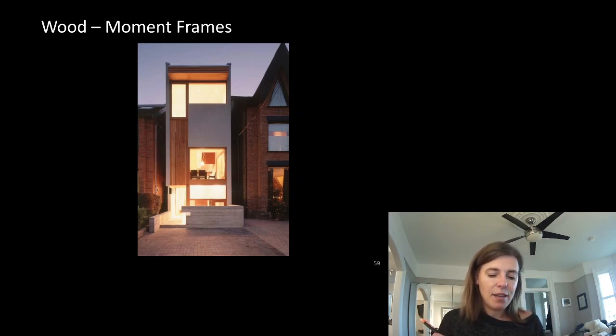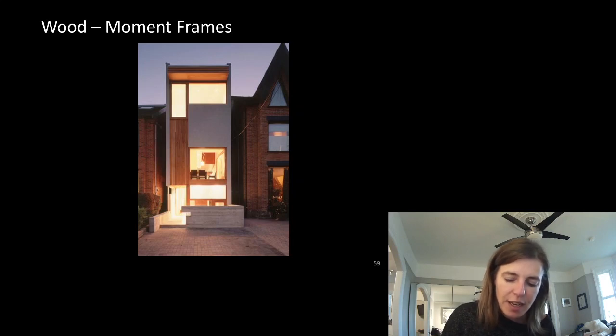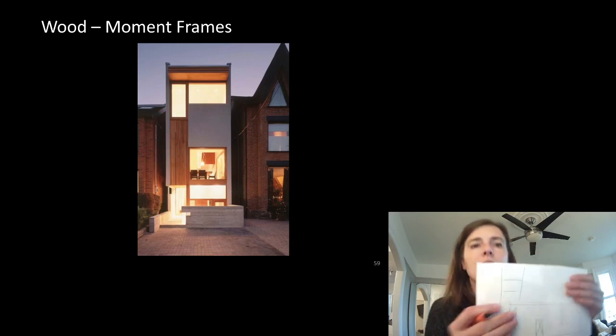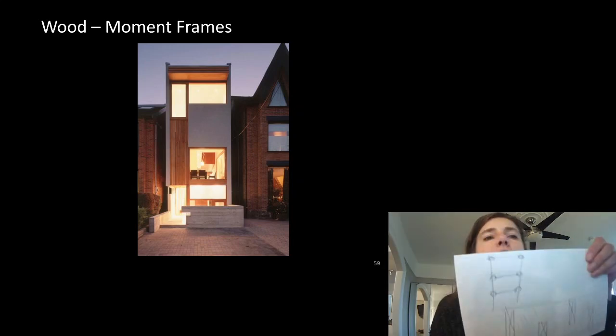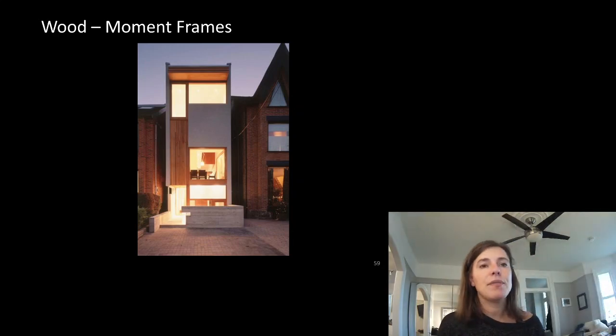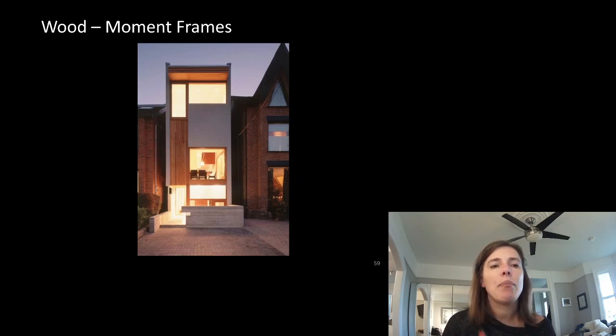And then, if I draw this in elevation, there's the ground floor, first floor, second floor, and roof. So if this is the plan, every one of those locations needed a ridiculous amount of specialty screws. I think it was like 12 specialty screws that were expensive, like not pennies, like dollars per screw, and 12 of them per connection, 6 times per frame, and these frames were every 8 inches. It worked. It was the only way they could build the house. So it isn't where we would have started, but it's where we ended up because there was no other option.